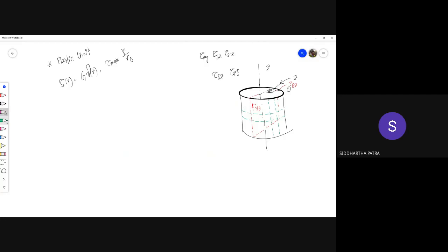So on this section I have this differential r0 d theta, and dz element, and in that element you have this shear stress situation, which means that at 45-degree angles to that, along this direction and along this direction, we will have the principal stresses.